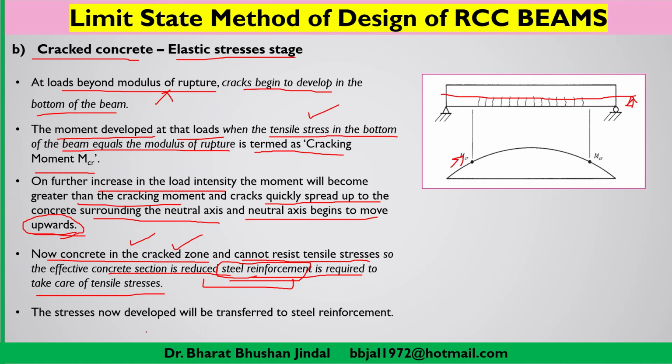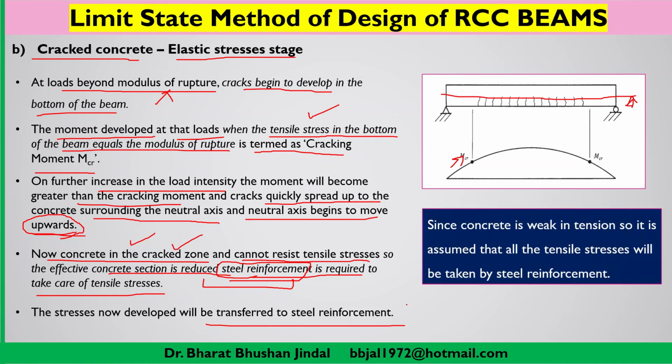So the stresses now developed will be transferred to the steel, and steel will start taking the tensile stresses. So here we can try to conclude that since concrete is weak in tension, it is assumed that all the tensile stresses will be taken care of by steel reinforcement.